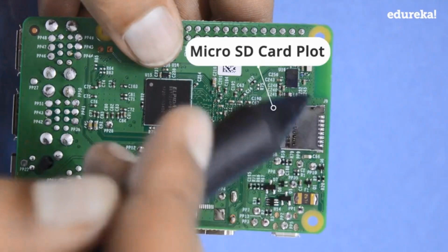So it's a micro SD card, and that is the memory. So you will typically have a 16 GB or 32 GB SD card. Don't go beyond 32 GB. So don't go for a 64 GB card. 8 GB is just okay, but I would prefer a 16 GB, because when you install Raspbian and you want to do something, then you'll be installing some stuff. So 8 GB will be consumed very fast. All your programs, operating system will reside on this SD card.